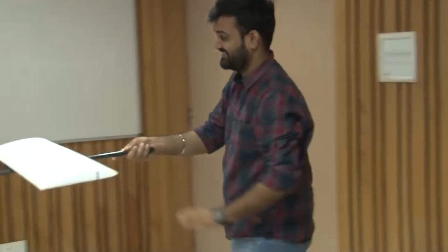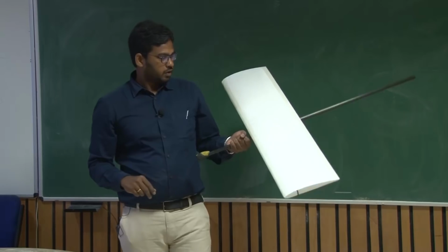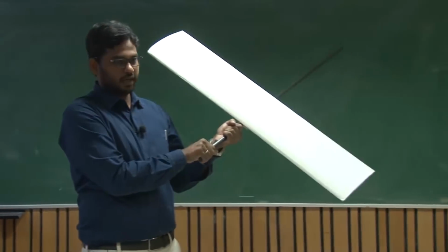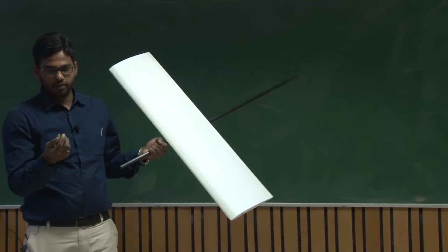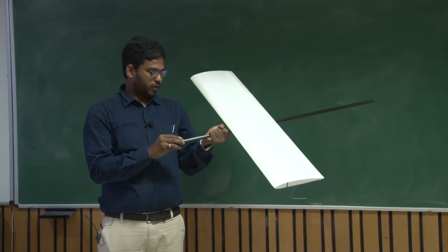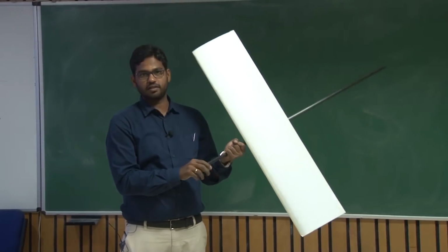See the glide? It plays a crucial role in this. So what is the reason it started flying as soon as I attached this clay? What must be the reason? We haven't changed the wing. All we did is shift the CG.